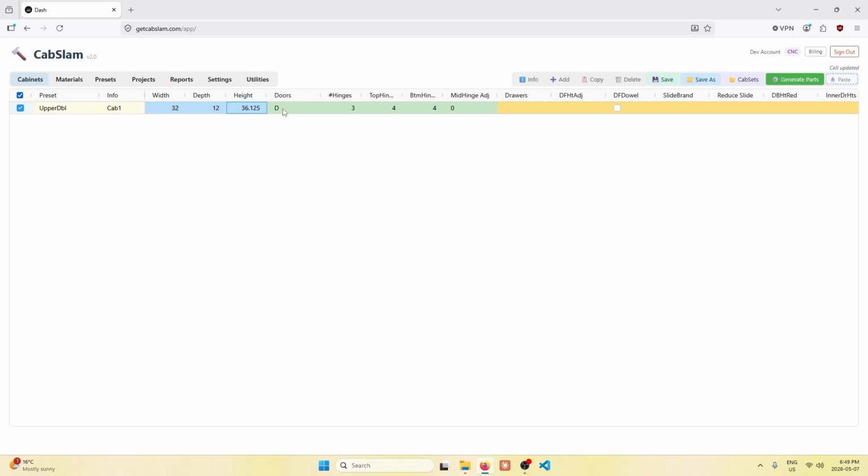If you wanted, you can actually change that to L or R, or T for a top hinge cabinet door. But we'll leave it at D for right now. And actually, we're going to change this to 65-ish, and then we can adjust the number of hinges. Let's call that 4 hinges. The setback at top and bottom, or the offset, is 4 inches each, pretty standard. And you can adjust all the mid hinges, whatever you like, in this cell right here. We'll leave that for now.